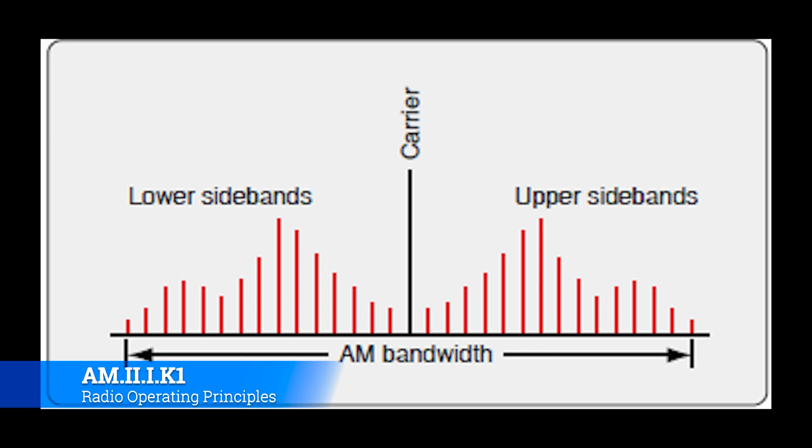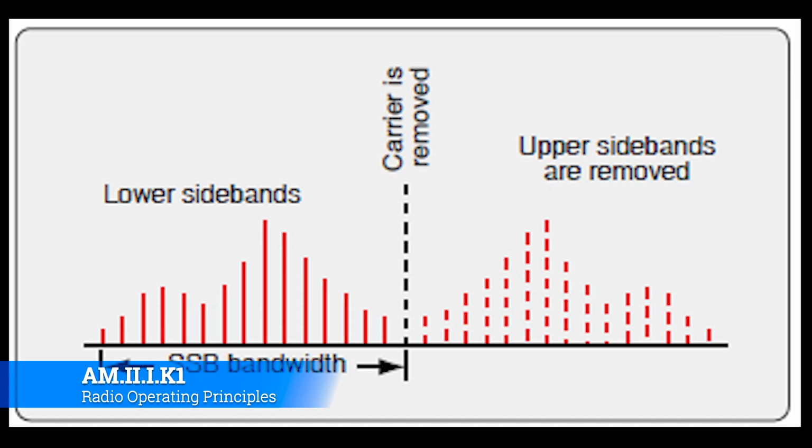Well, to prevent that problem, you have spectrum management, and single sideband radios try to help manage that spectrum effectively by basically cutting off half of a signal, so that you can use that other half for something else, and you don't step on one another. So let's look at another graphic. All right, so here's the thing: you don't necessarily need all of that bandwidth, and so in order to be as economical with the bandwidth as possible and help deconflict as much of the spectrum as possible, the lower sideband is actually what ends up getting used.